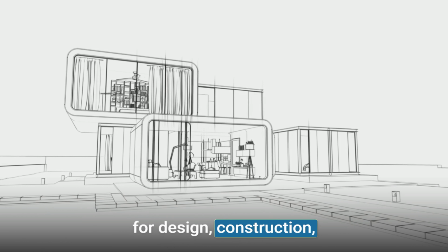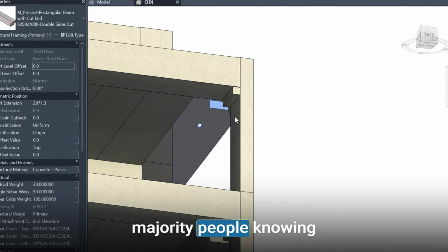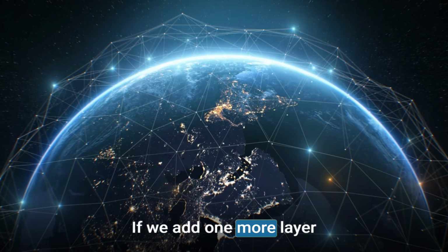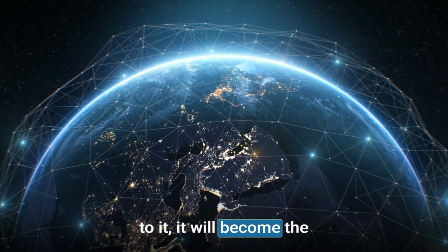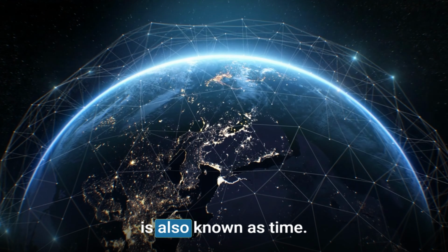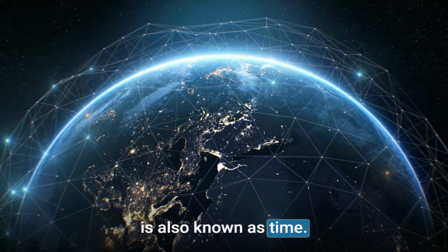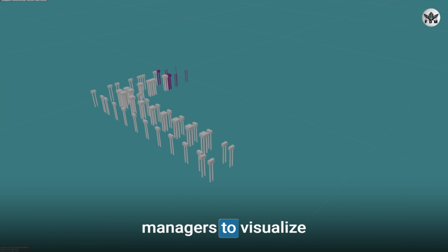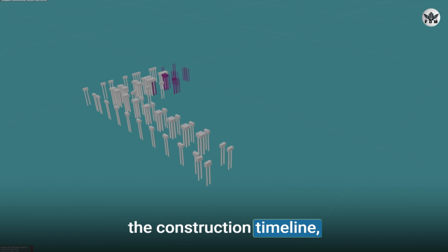Up till now, things are really normal because the majority of people know this much about BIM. But if we add one more layer to it, it will become the fourth dimension, which is also known as time. Time adds another layer of complexity by introducing the element of scheduling and sequencing. 4D BIM enables project managers to visualize the construction timeline, anticipate potential delays, and optimize the resources accordingly.